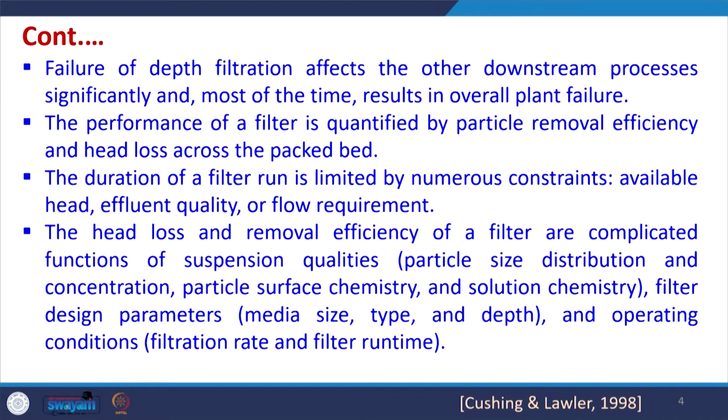If any depth filtration unit fails and is not filtering the suspended material, it will affect the downstream processes significantly, and most of the time it may cause overall plant failure also. If the pressure drop increases too much, there will also be a lot of effect on the overall efficiency of the plant. So, the performance of a filter is quantified by the particle removal efficiency and head loss.